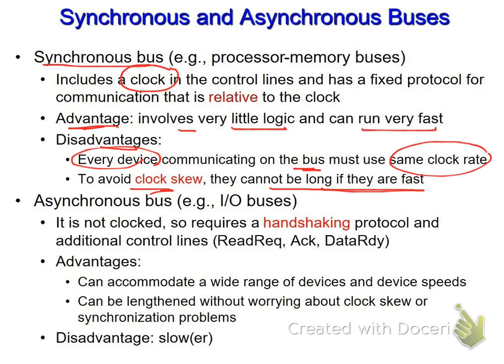Okay? And if I have a very fast clock, this will make a problem. And that's why I have to take care of something like that when I'm designing my circuit. So if I have the CPU and any nodes that interface with that, if it's too far and I have a very high clock, then it might be a problem. And that's why this is also another limitation with the high clock rate.